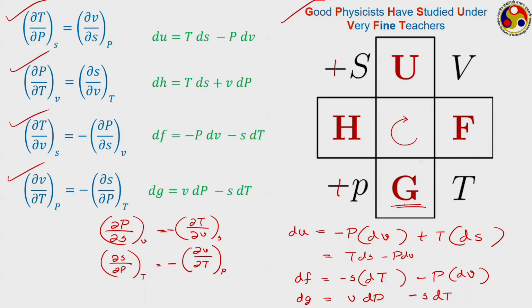But we started with the objective of developing relations of du, dh and ds. Of course, Gibbs equations are there, but if you see here, the equation for du also incorporates ds. Similarly, dh incorporates ds. So, now we have to make use of this Maxwell's relation to update this Gibbs equation, so that we can replace this ds and write this only in terms of T, p and specific volume.